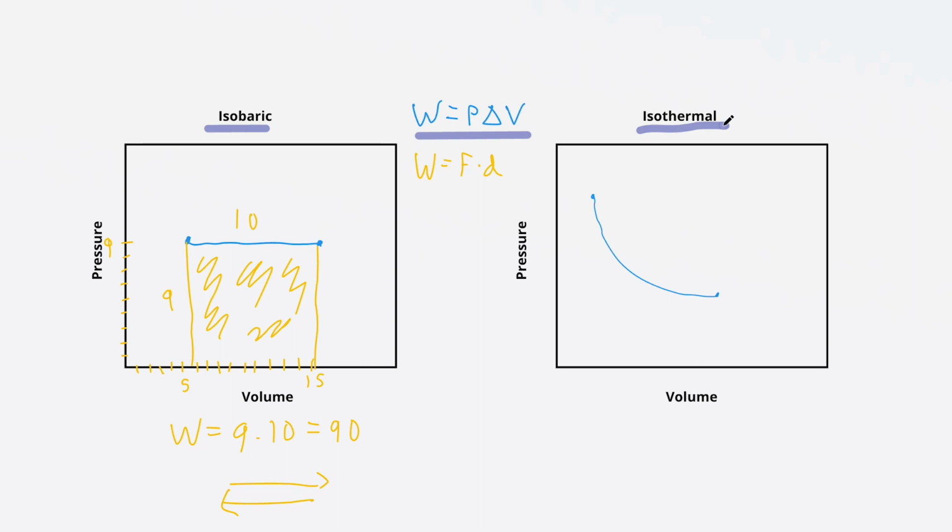And how you do that approximation, you want to start just by drawing your vertical lines down, and then turn that into a rectangle, and then a very approximated triangle. And then from there, you would find your area of the rectangle first, and then the area of that triangle, and add them together. Just keep in mind that that triangle is not the actual area. That's not going to be an accurate area, but it should get you at least close enough that you could compare it to one of the answers if you ever have a question like this on the test.